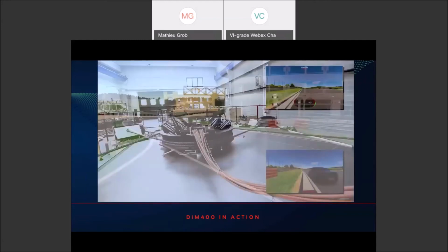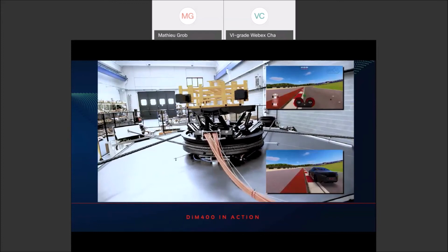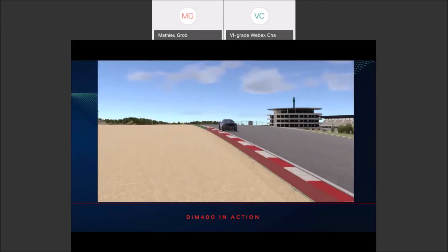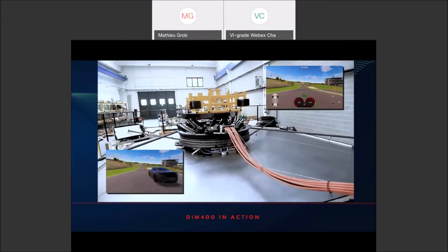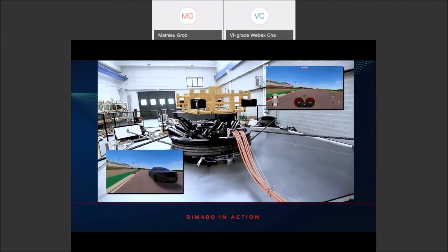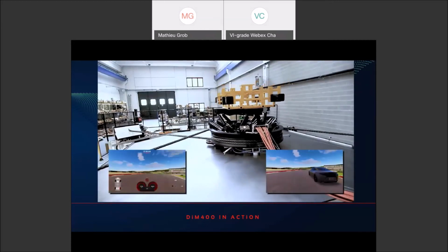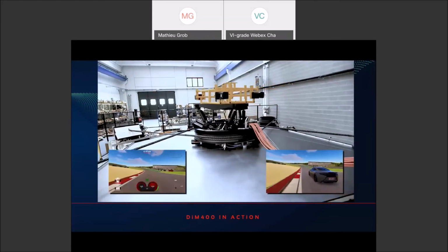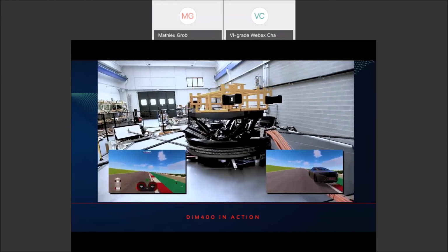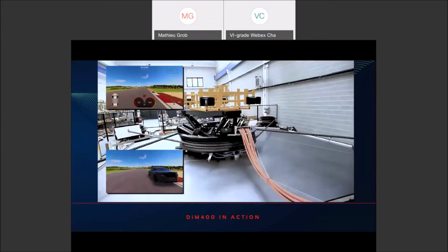Here, due to the cable system, you can still have a lot of yaw and, while you are doing a very big amount of yaw, still have a big lateral displacement at the same time. So you have really more capabilities, especially in combined acceleration and yaw, than the previous system due to the cable system and the extended workspace. And also, you can see that the upper platform Z capabilities can be very, very high. Because of the even better decoupling between the different degrees of freedom, we have increased the Z capabilities, the vertical capabilities of the system.